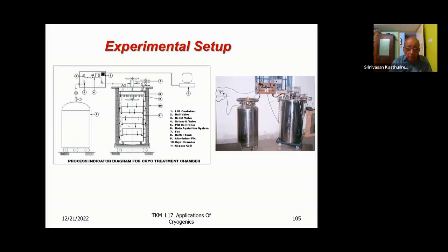Okay, you have a liquid nitrogen flow coming into the system from the storage dewar. It cools an upper chamber and then the vapors go out. The upper vapor in turn cools and circulates the gas load which is present within the chamber by suitable means. So the whole zone which is kept here becomes completely cold. Okay, it reaches the cryogenic temperature, the appropriate temperature, whatever is designated.